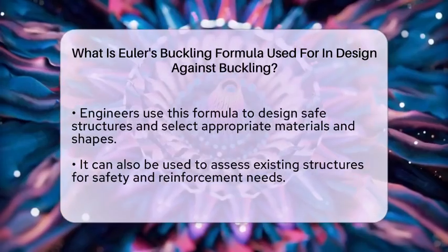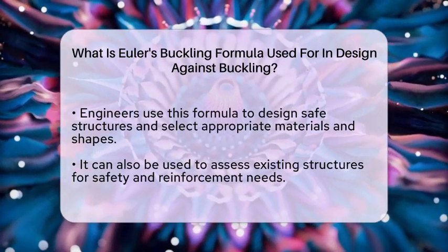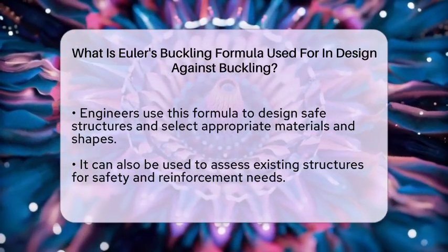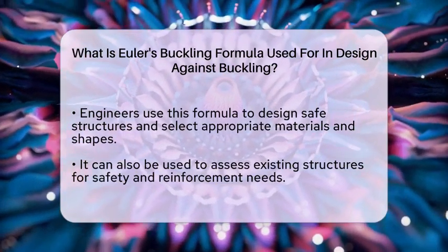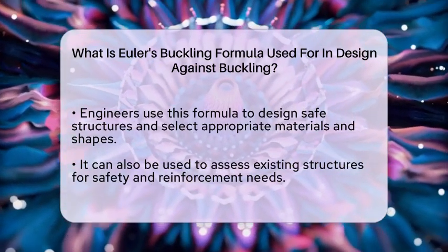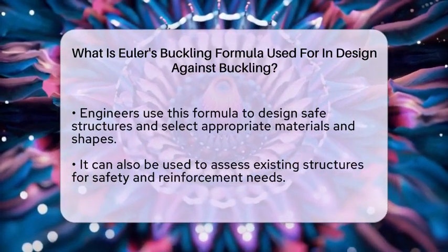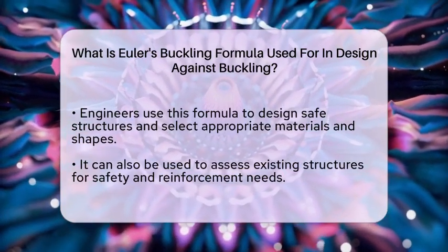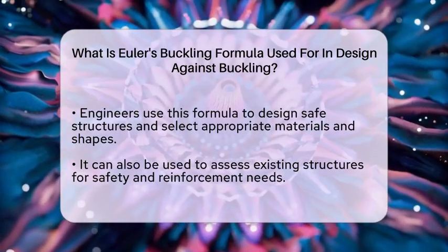The formula assumes the member is initially straight and that the load is perfectly aligned along its axis. It also assumes the material stays within its elastic range, meaning it doesn't permanently deform. These assumptions make the calculations reliable for initial design and safety checks.